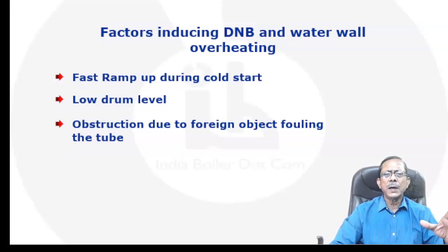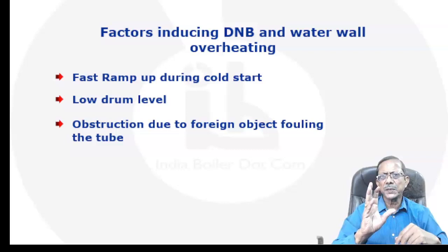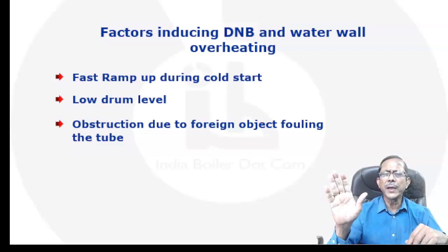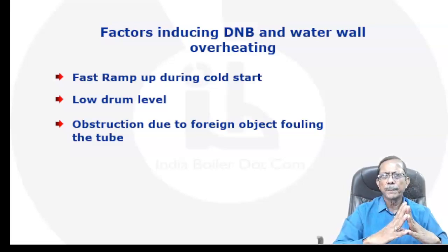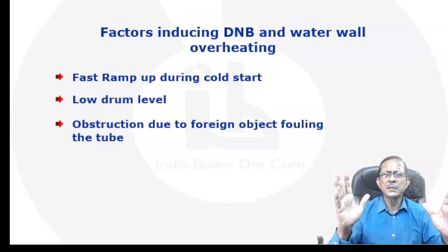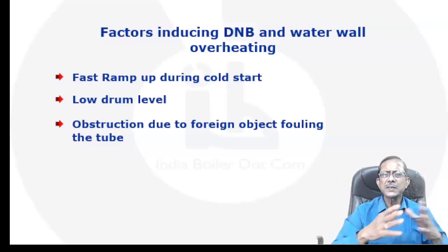In fact, a boiler, after a long shutdown, immediately after the start, it has failed. There was a large bulging and fish mouth type opening in the water wall. Now this is a particular kind of incident which you see quite frequently everywhere. Whenever that happens, always understand that something has gone wrong during the shutdown, and this is a clear case of obstruction in the water wall. I have numerous such experiences of cases where this has happened.